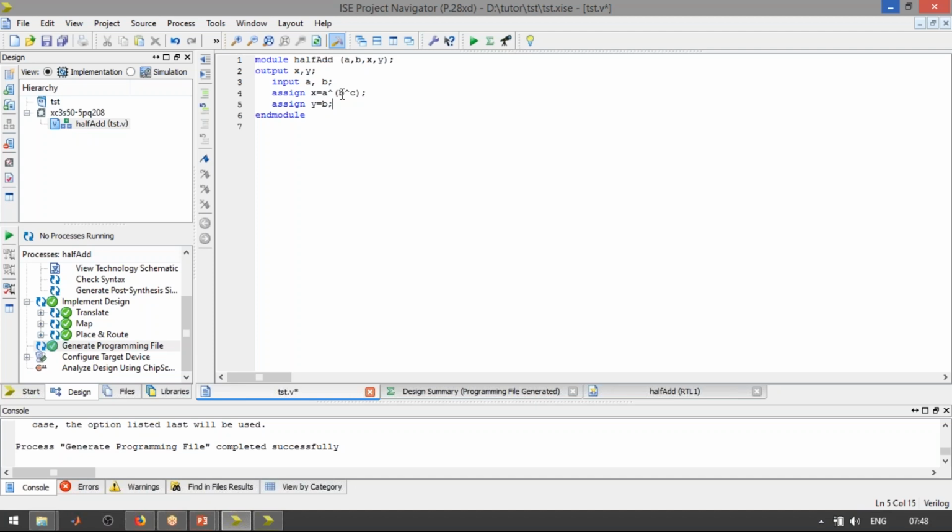But for example, if you want to create a transconductance amplifier, there's a particular way to design it, right? Actually, that's an analog device. Hardware description language is purely for digital design alone. If you want to design a transconductance amplifier, then we have to go for SPICE simulations or transistor level design.